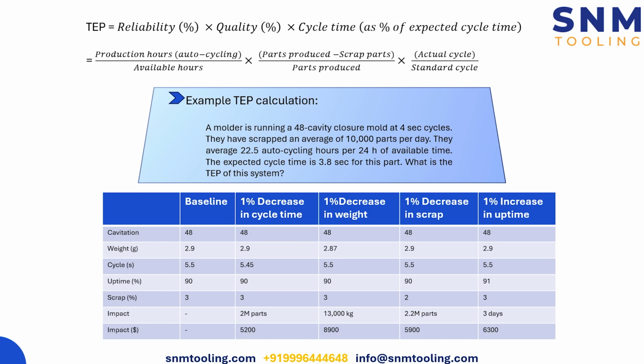If a mold is able to work quickly and mold a high number of parts, that means the cycle time is less. But the mold requires significant downtime and significant maintenance. There are chances it can break down, the downtime is high, there are several issues, and it is not able to sustain the production. So that mold is not an ideal mold.